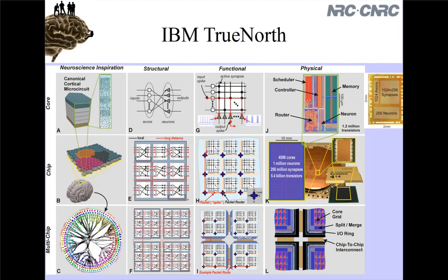And then you can do some fun trickery to group a few neurons together or group a few synapses together, in order to get maybe 4-bit weights or 6-bit weights and things like that. But when you do that, you start having fewer than 1 million neurons on a chip. So that was, I think, one of the first big industry players in this space. And it ended up being just difficult for people to use.